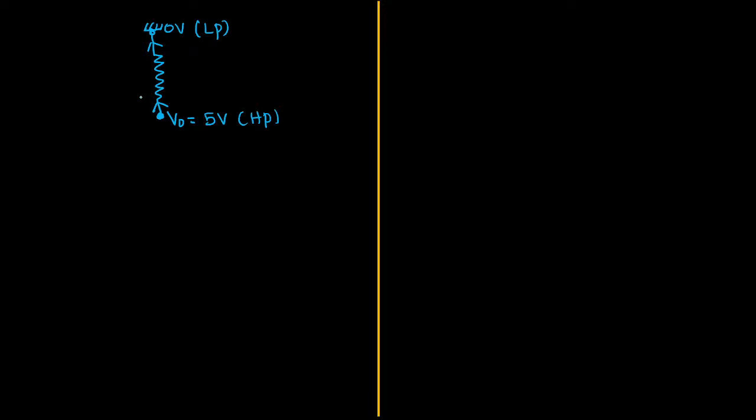So from here I can say this is the direction of the current. Resistor is a passive element, so current entering point is plus and leaving point is minus. This is the collector resistor. Current flow through the resistor is IC. Now I just wanted to know the voltage drop across the resistor. I am calling it VC. When writing VC, there are two ways.